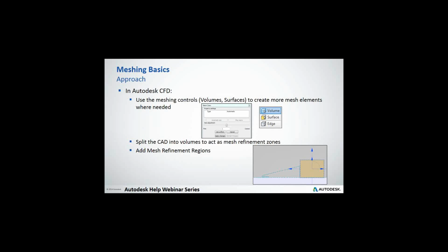But sometimes you have thin solid parts. When I say thin solid parts, that means you have a thickness of, for example, 2 millimeters. In this case, I would recommend splitting the thickness into 2 parts so that you make sure that you have at least 1 node through the thickness.